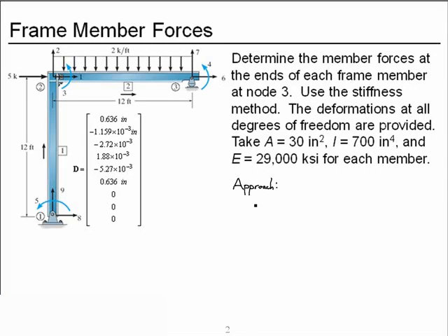We picked a determinate frame so that we can find these member forces by using just the equations of equilibrium. And we did that because when learning a new analysis method, either a hand method or computer method, we should always first use it on a problem for which we know the solution. That way we can confirm that we understand how to use the method properly, or if we're developing a method, we can confirm that the method works properly. So that's how we'll start.